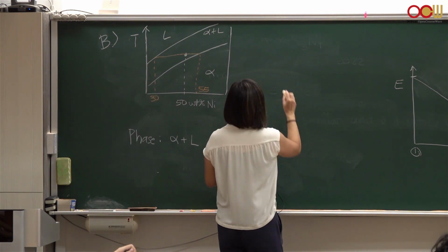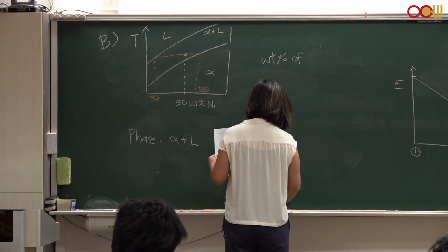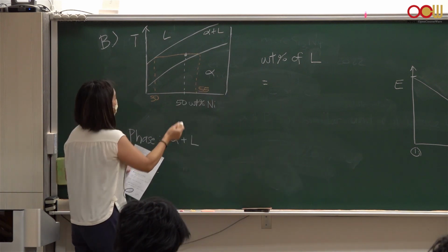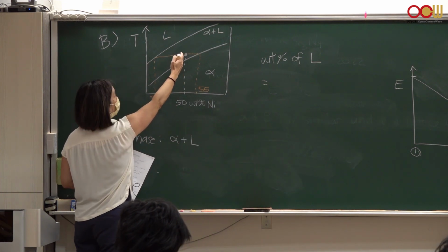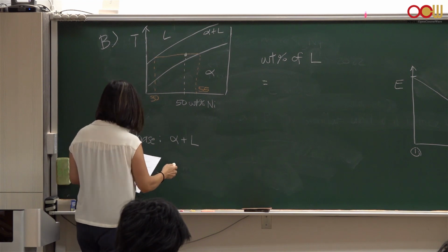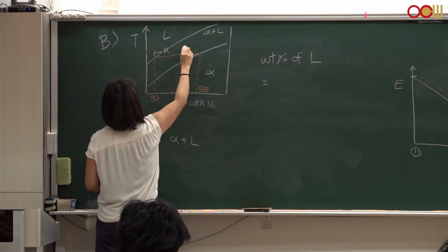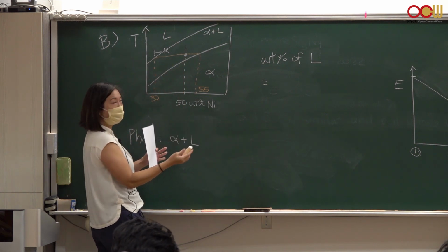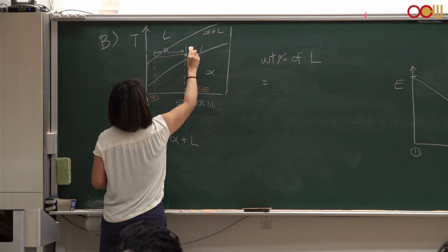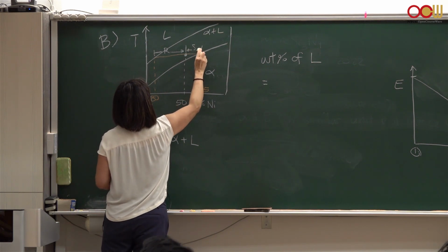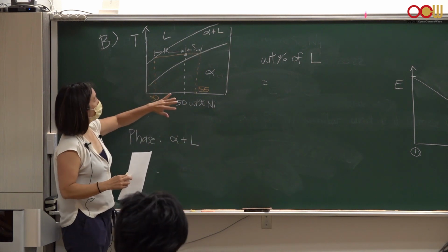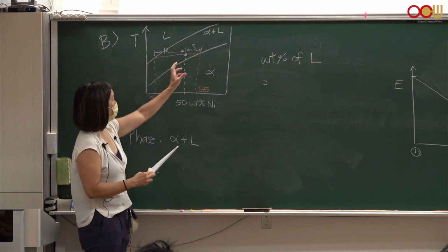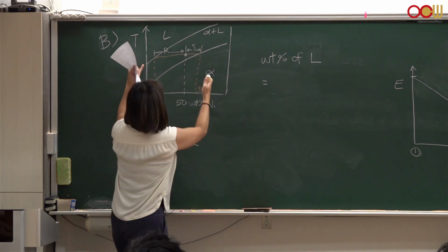All right, so the weight percent of liquid phase is equal to the distance of that line to the opposite phase. So if we call the length between the liquidus line and where our material is R, and this distance S, the amount of liquid is the distance to the opposite phase, S, divided by the entire length of that line.